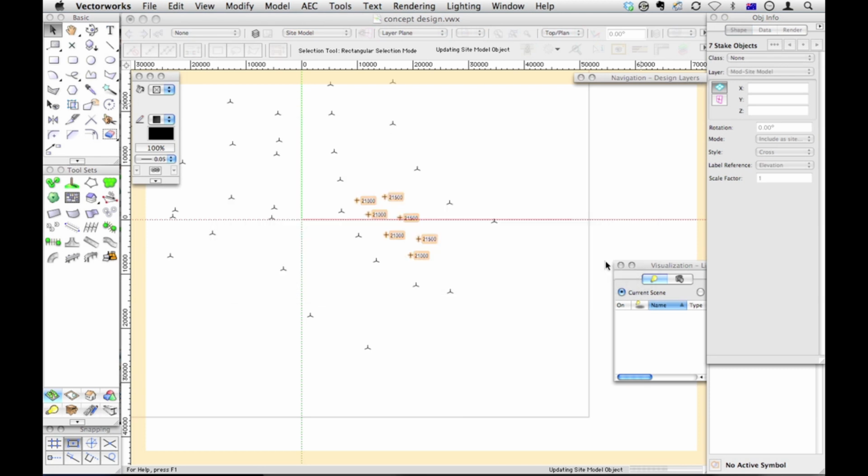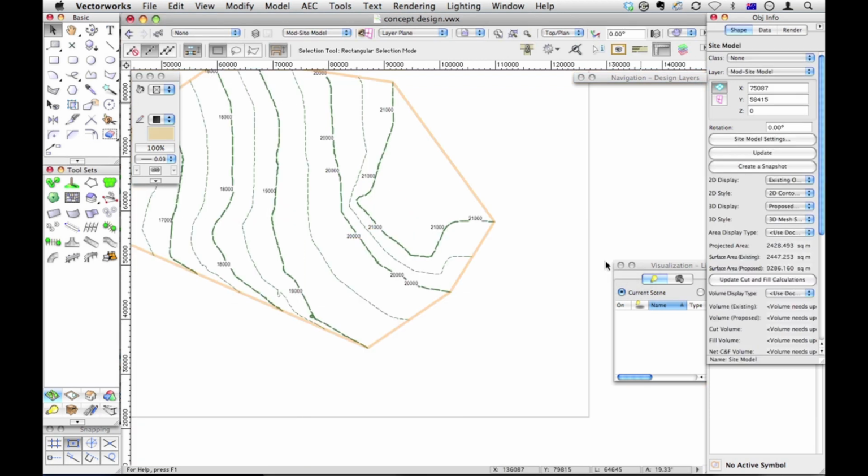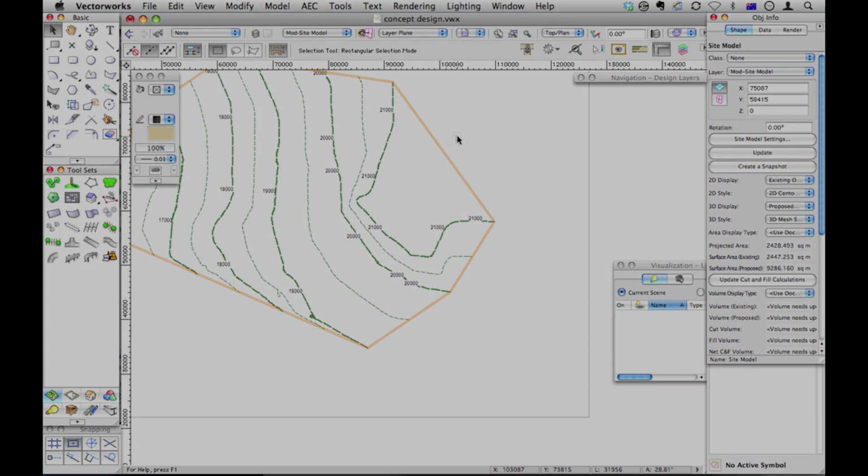Don't worry about that dialog. So now you'll notice what's happened is we've got quite a steep little climb just here and then it flattens off the site. That's how you edit the source data to get the source data up to date. Now this doesn't include modifying the site, which would be done by pads and roads and stuff like that. This is just getting our existing terrain to be correct.